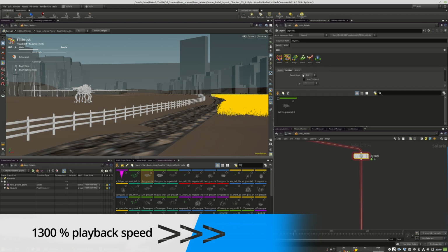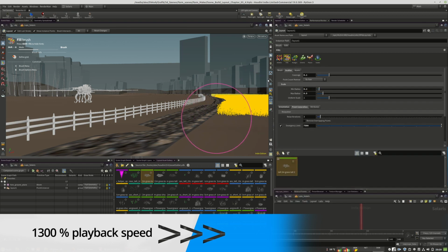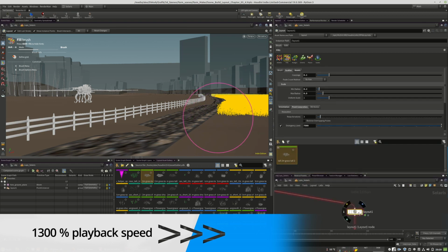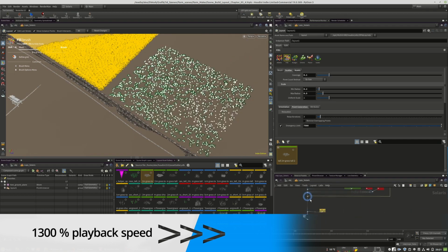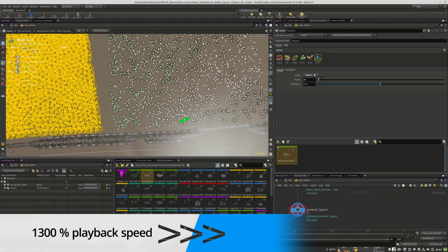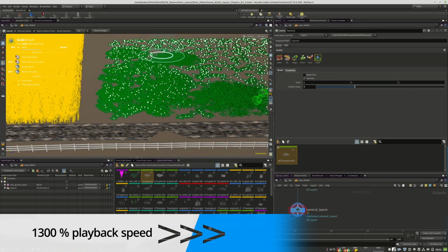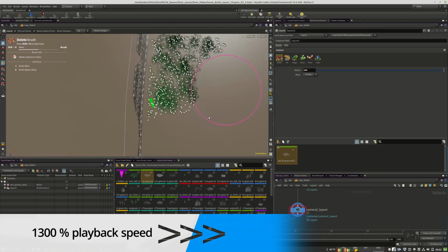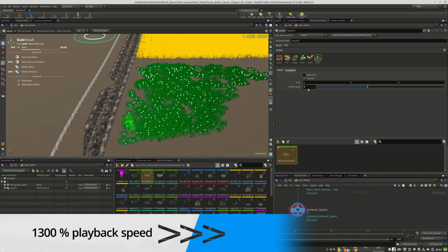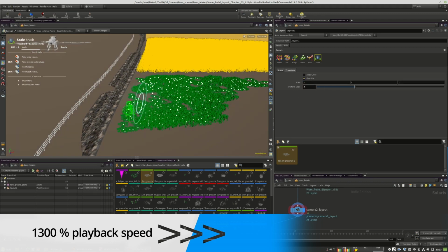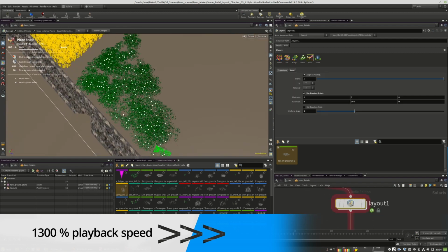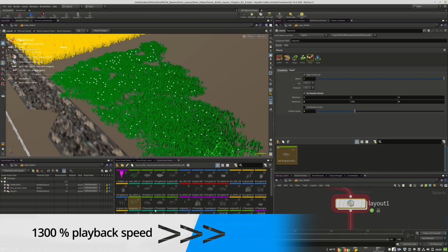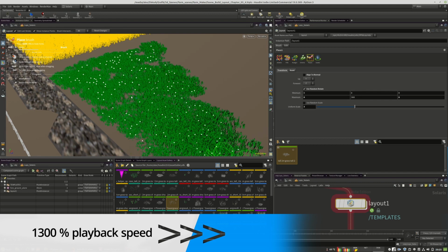I tried different values, and I have to say it's sometimes very hard to find the best settings in the first place, so you have to play with those values. Here I have deleted everything that is not in the image, and then I increased the quality and added more grass placed by hand with the placement tool.